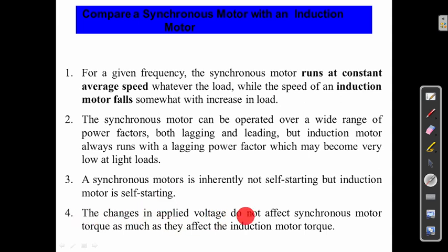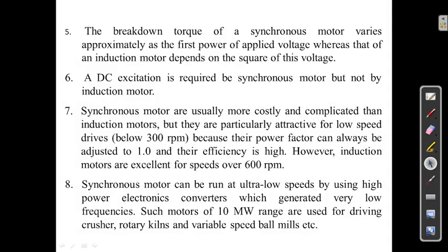Then changes in applied voltage do not affect the synchronous motor torque as much as they affect the induction motor. In the induction motor it will affect the torque, but here it won't affect the torque. Then the breakdown torque of a synchronous motor varies approximately as the first power of the applied voltage, whereas that of an induction motor depends on the square of this voltage.